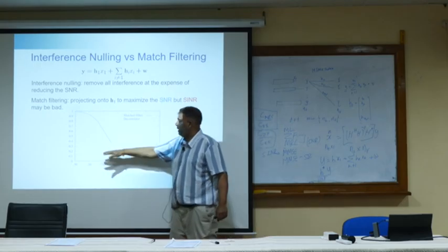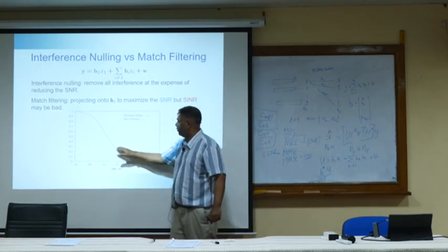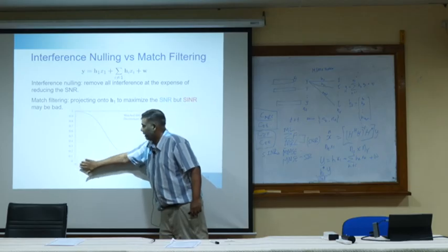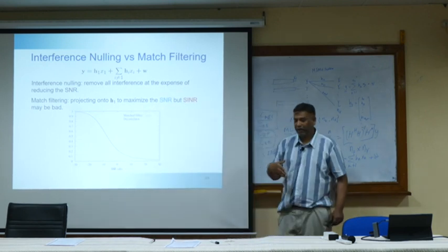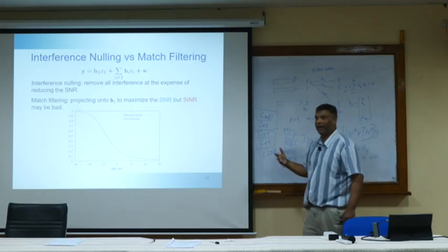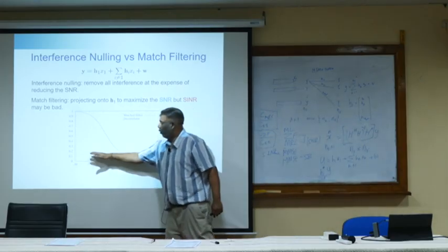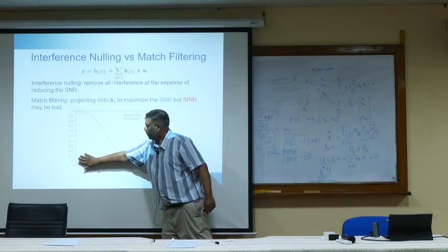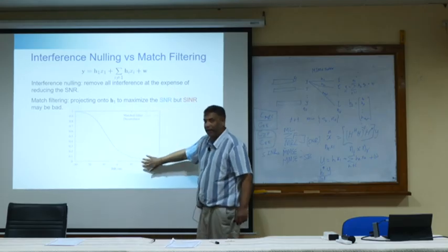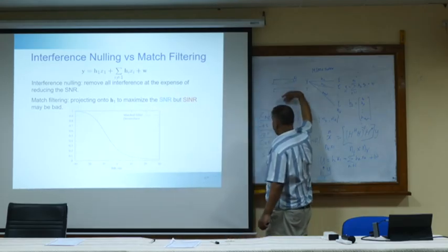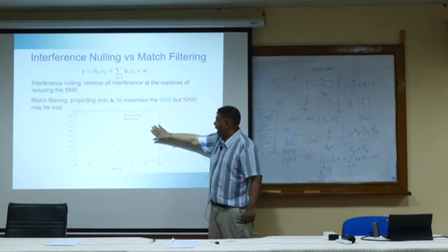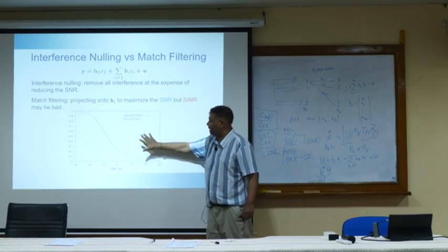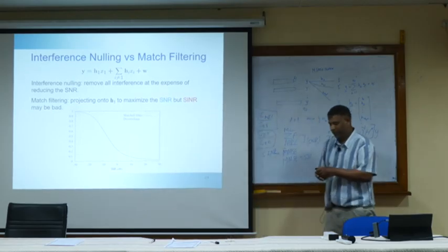Similarly, the decorrelator or zero forcing normally cancels interference, but at low SNR there's no interference, yet the receiver is built to cancel interference. So we are applying an over-conservative solution, and the performance is bad. But at high SNR, the interference will be there between the streams. The zero forcing will cancel that interference and performance is better. That's the message from this plot.